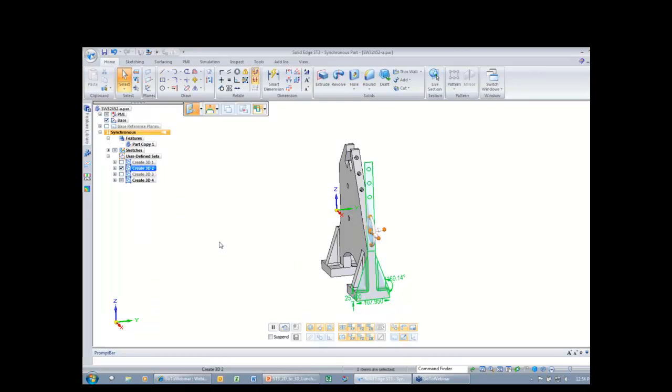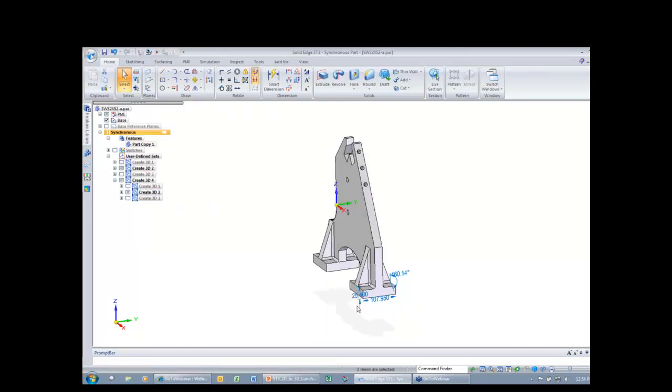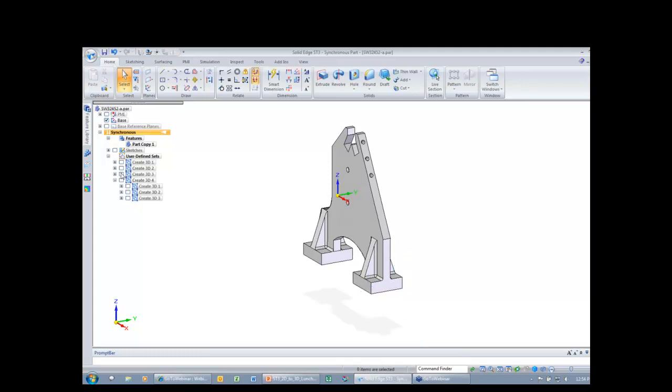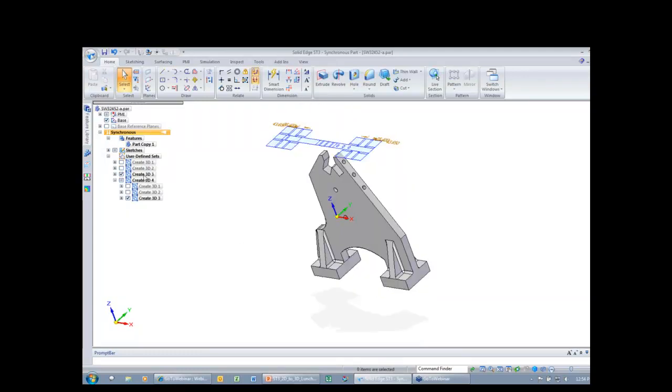I'm going to attach the PMI there again, and notice if I change this 25.4 dimension, notice how it's changing the other side. The other side is getting longer too because of coplanar and also symmetry in this case. So maybe I want this to be 35. The top one, let's go ahead and just right click and attach the PMI of that one as well.